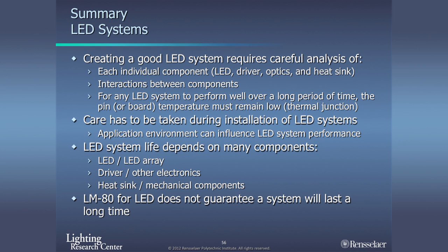So, when you think about LEDs, you have to think about all of the interactions in the system. It's not just lumen depreciation, so it's not just LED life. There's the array, the driver, everything else. And the LM80 standard just doesn't cover those things. So you as a consumer have to be wary.